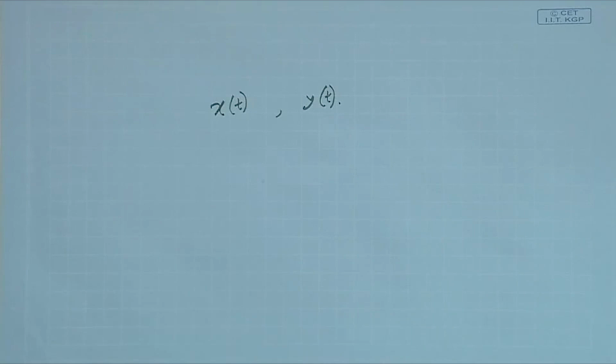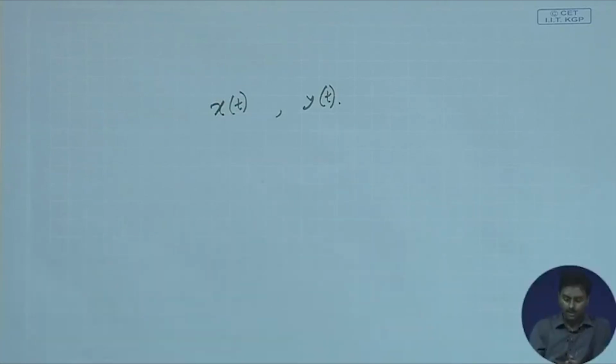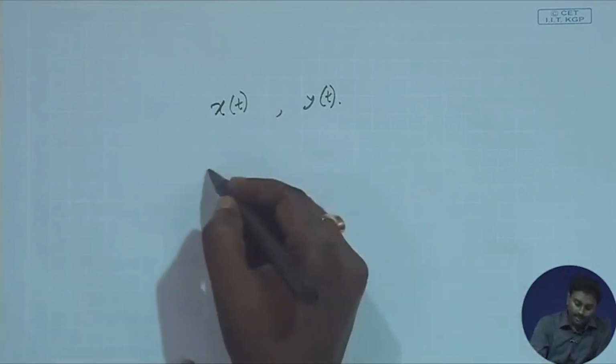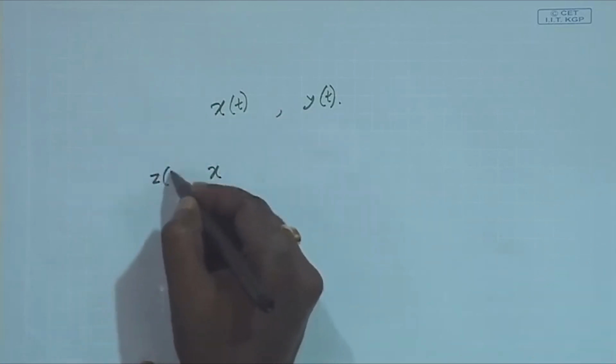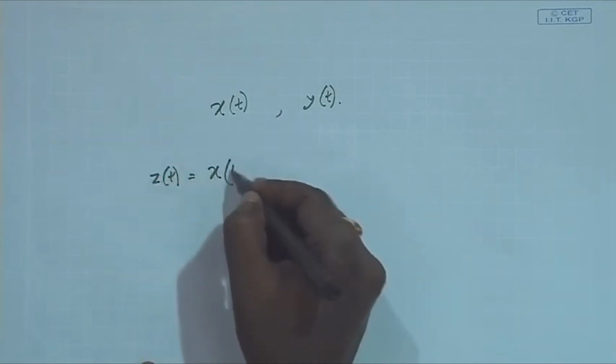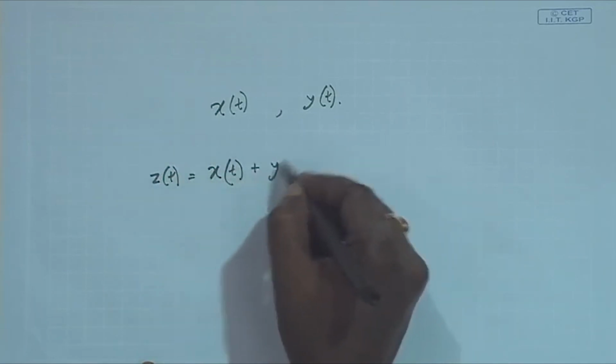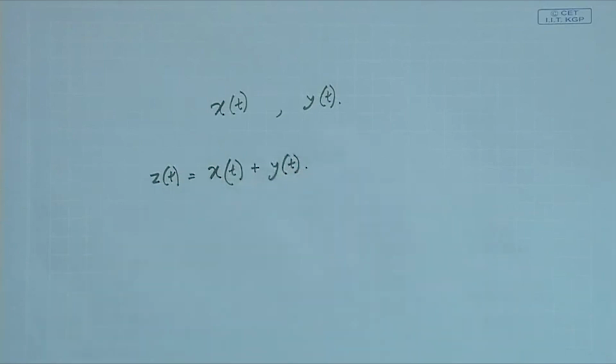Okay. So, we are just assuming two very simple signals which are orthogonal to each other. It might be just like cos ωct and sin ωct. We have already proven these two signals are orthogonal within a particular period, right, if it is defined from minus pi to pi. Okay. So, take these two signals and let us say I wish to generate another signal z(t), which is just an addition of these two signals.